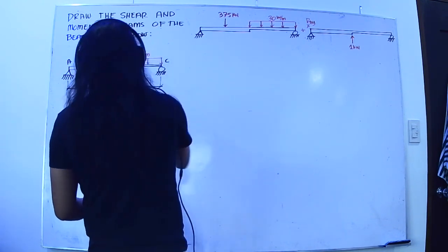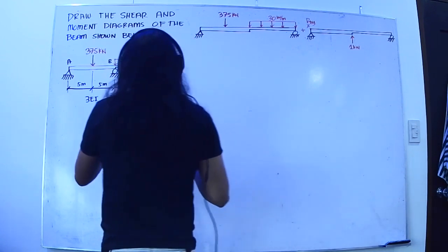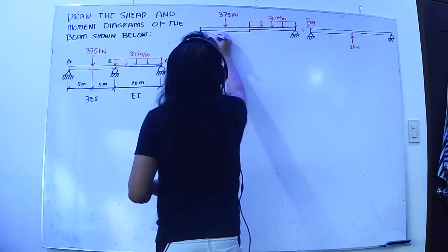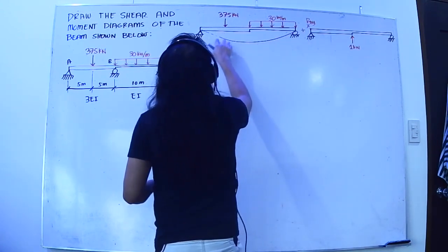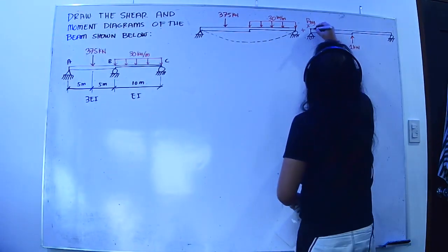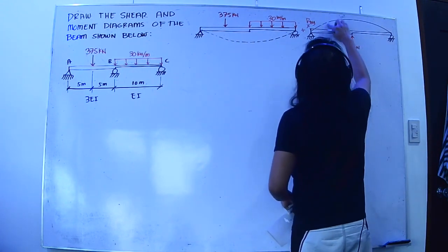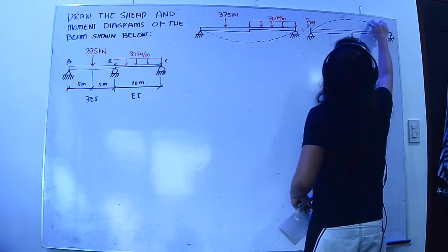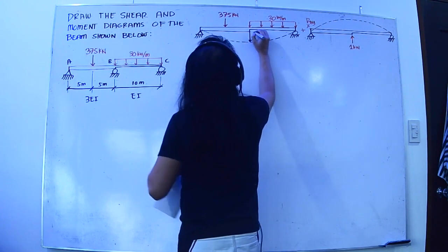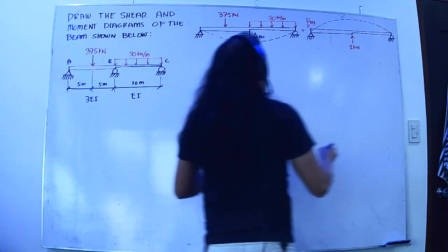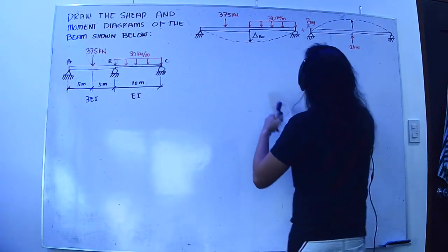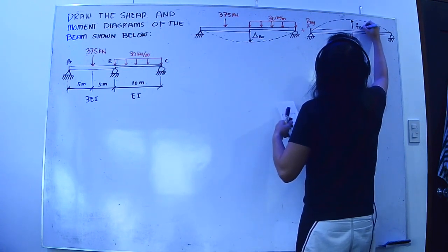You can also choose C or A, but I'm more comfortable with B. Now that I've picked this apart, I'll draw the elastic curve. The deflection here is equal to delta BO, and the force here is FBO.